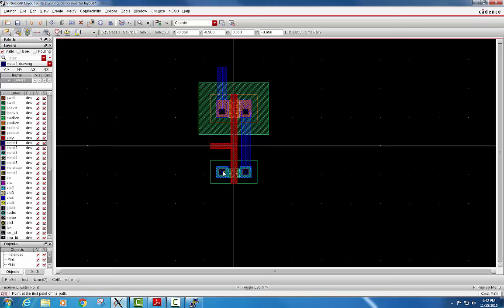Again, the left pin from NMOS is the source for NMOS and which is to be grounded. So for now we have created the layout for our required design, but we are left with two more things, and that's the body for PMOS and body for NMOS.